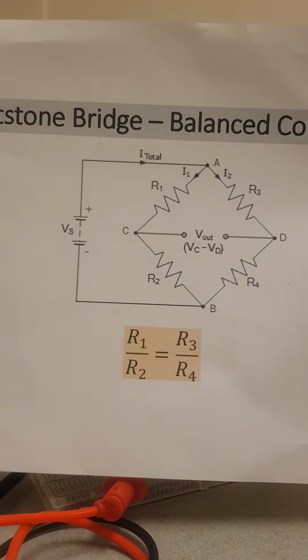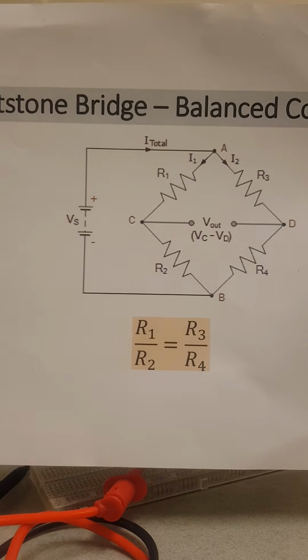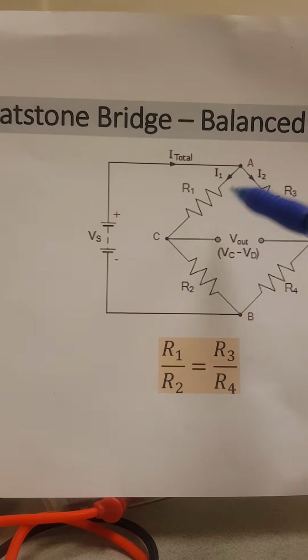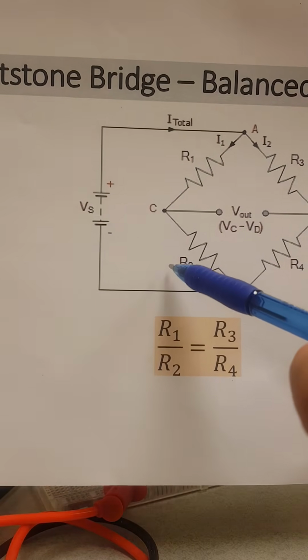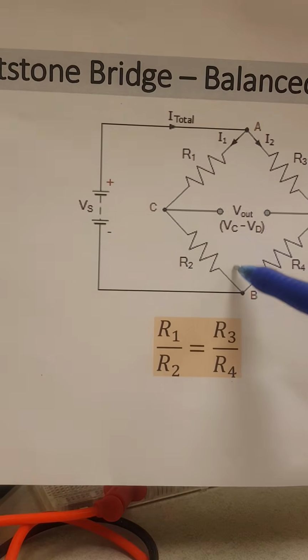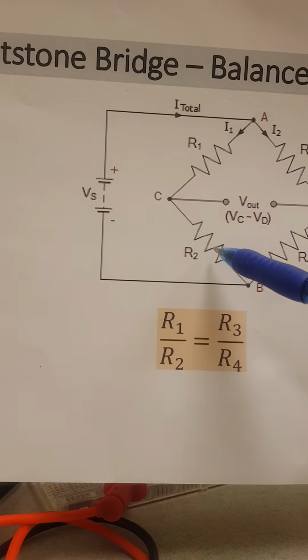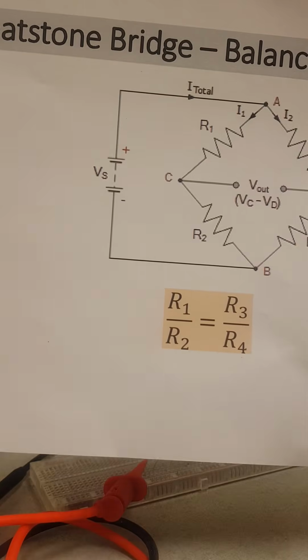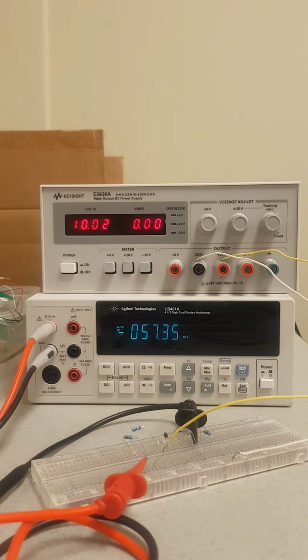So now ideally we are in this situation where the Wheatstone bridge is balanced. So this is around 11 kilo ohm, 11 kilo ohm. So our thermistor is in R2. Okay, so this is 11 over 11, 10 over 10. So we are in balanced condition, and the voltage is around 0.